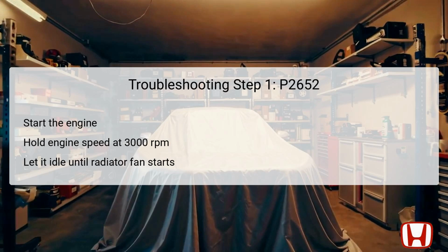Observing this sequence helps determine if there are fluctuation issues within the engine's oil pressure management system when the rocker arm oil control solenoid is not engaged. After this, you should let the engine idle to stabilize its systems. This initial procedure is fundamental for establishing baseline parameters before further inspection of the rocker arm oil pressure sensor and control valve can be effectively carried out.